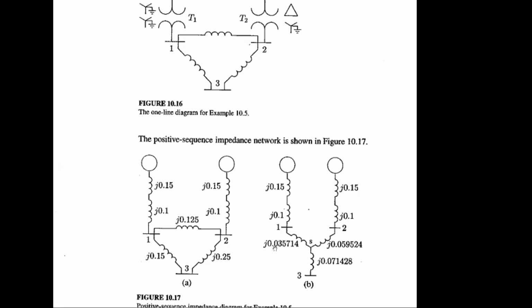For this first part, multiply these two and divide by the summation of all three. Only one part you can calculate so that you understand the first part, and repeat that process for the other two also. Have you got the equivalent Y branch?